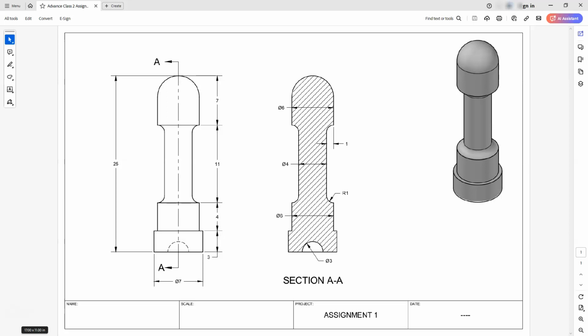In this video we're going to be taking a look at another revolved part. One of the more important things to remember is how you set it up. One of the things I like to do just to make things easier is to always adjust my axis to the longest, tallest dimension of my center line. So that's what I'm going to do first, and that's my pro tip for this video. Alright, let's jump right into it and get it started.